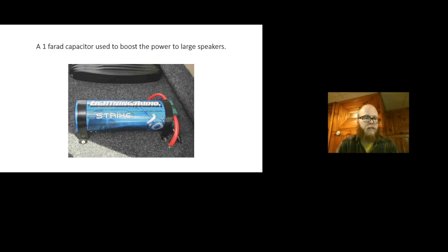So there's a capacitor that's built into the circuit to act as a second battery, a battery that can charge and discharge very, very quickly. When you install one of these in a vehicle, they often will send a resistor or a light or something like that, because if you hook the capacitor up without any kind of resistance in the circuit, it'll often spark a whole bunch. Sometimes it can even really hurt a battery.